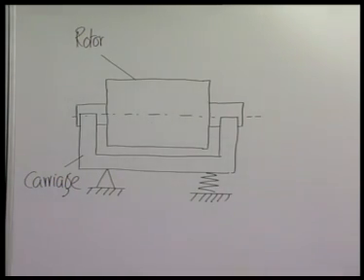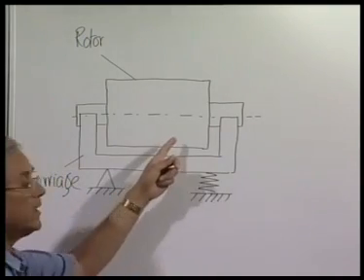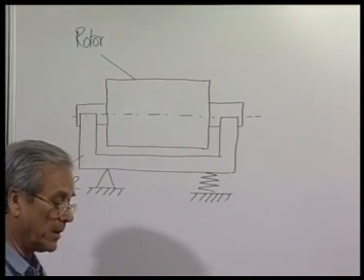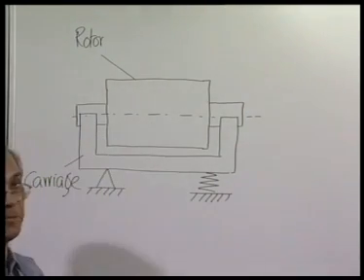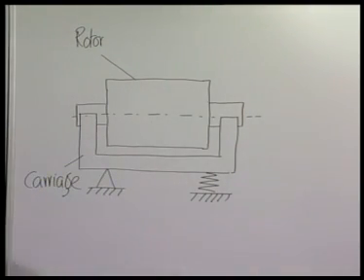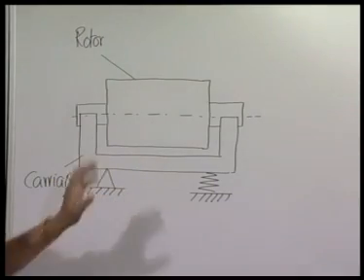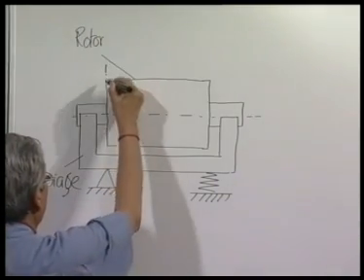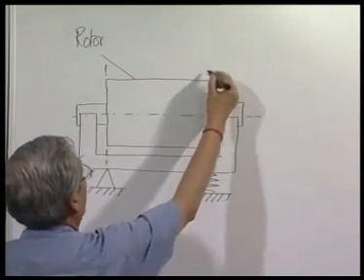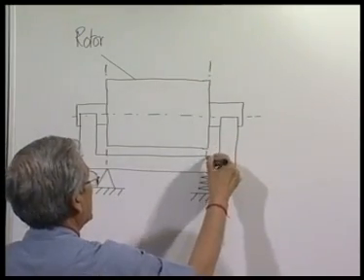Now, once this rotor starts rotating, the centrifugal force or unbalanced inertia forces will start appearing, depending on the speed of the rotor. Here we may assume that the complete unbalance of this rotor is represented by two masses, one in this plane and the other in this plane, just as our choice.